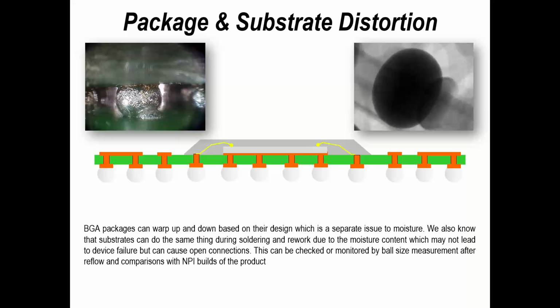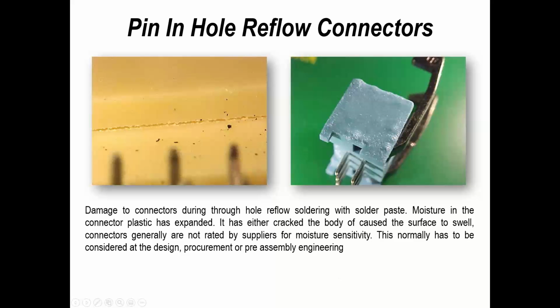So what can happen during the soldering operation is board or component warp during the soldering operation. So they're not in contact with the solder paste. The solder paste reflows, the ball perhaps settles back down as the package starts to even itself out and go back to its normal position. But if there isn't sufficient flux left within the solder paste or on the surface of the solder paste, you get a head-in pillow or head-on pillow type open circuit. So again, you can see there are 3 or 4 things there that are impacting this particular result.